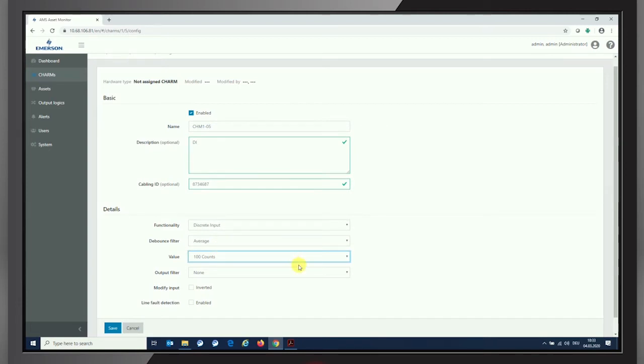So it starts counting the pulses as long as the input signal is true. So it starts until 100 before it provides this information to internal processing, or if we would have set up 10 counts, it's just 10 counts. And it goes the same way, different direction. So if a signal is true and becomes deactivated or false at the input stage, it needs to count back to 0 before the internal processing detects and processes the 0 detection finally.